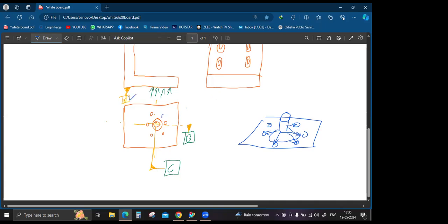Okay. So right now, all the hole positions will be controlled by the position tolerance, I am giving 0.02. Okay. So the first surface will be A because on this surface we are machining. So that will control the perpendicularity also, A, B and C.